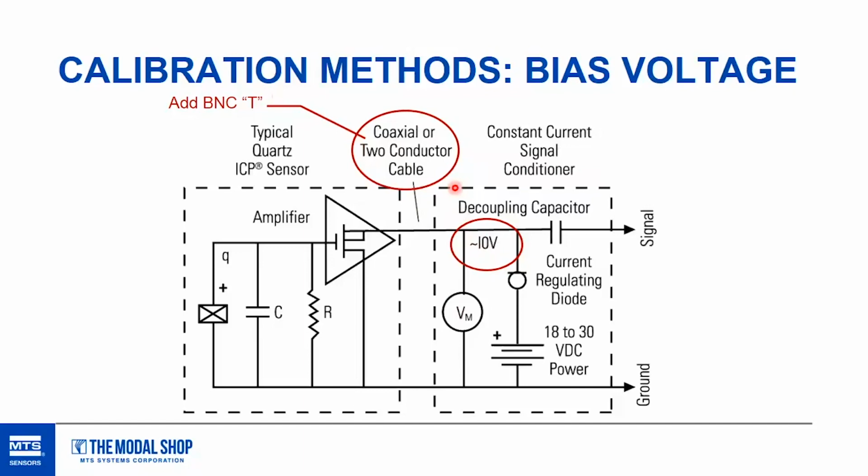What happens is you'll get humidity that will enter the cavity of the accelerometer, and it's going to change that bias voltage in proportion to the humidity. I've actually done that kind of recently, just looking at laboratory humidity environment. Oftentimes during a calibration, we're going to record temperature, humidity, and pressure. If you plot that versus bias voltage, you can actually see a difference there between the humidity in the room and the bias voltage output that you're getting.